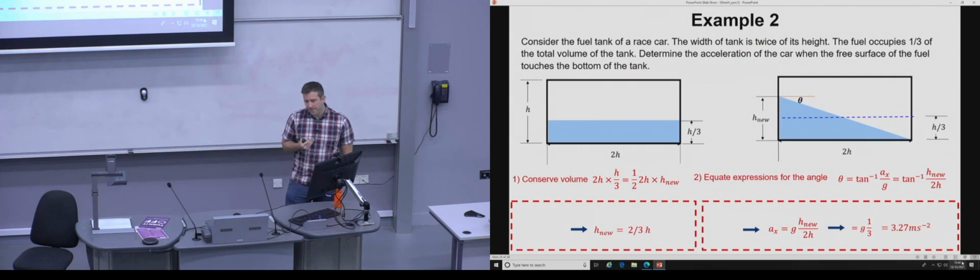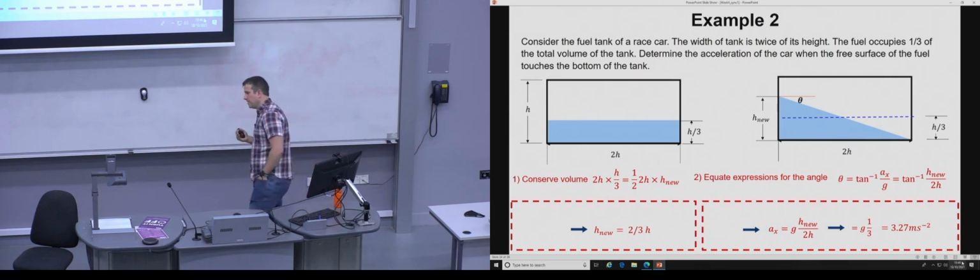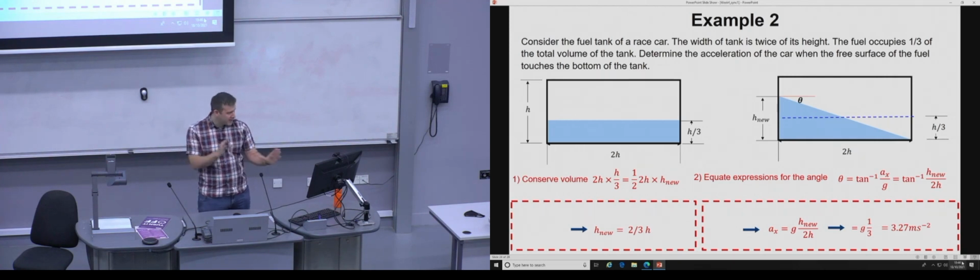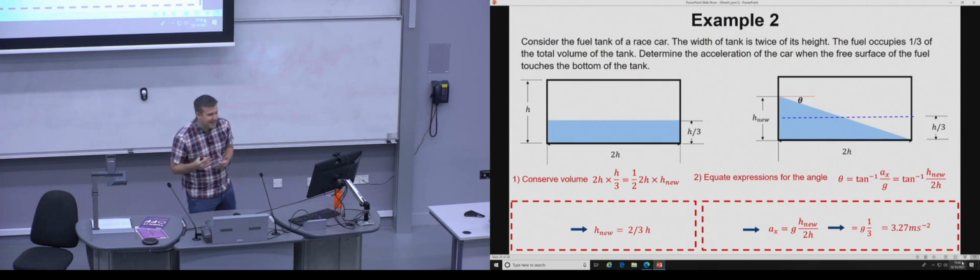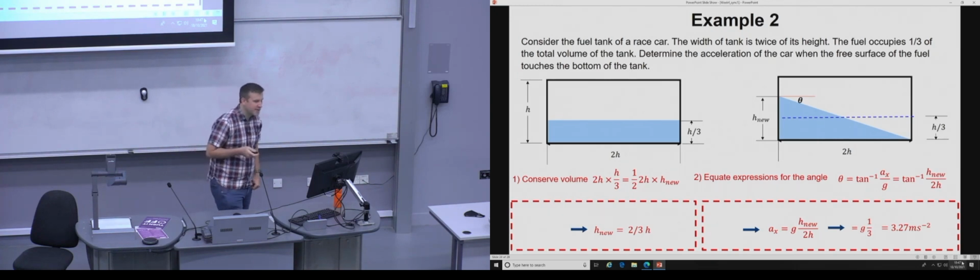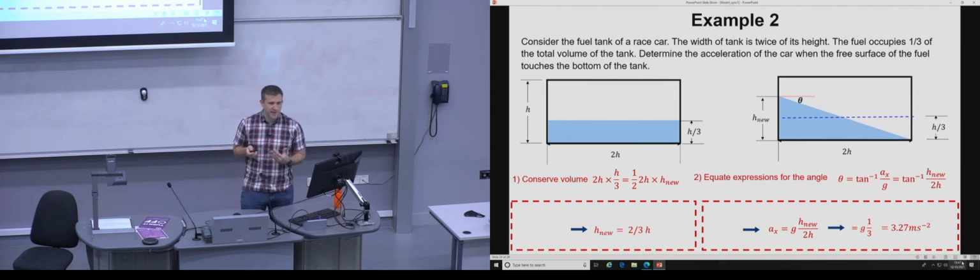Again, this is a significant assumption because we're assuming that it has time to reach this state. But at the same time, this is a back-of-the-envelope calculation that you can use as an engineer in this domain to get an order of magnitude to find out what problems you might encounter with a fuel tank design. So it's already becoming something that is being used in an applied way.